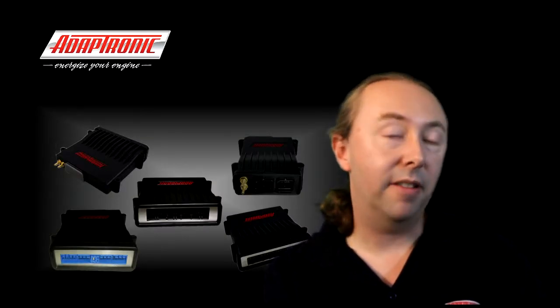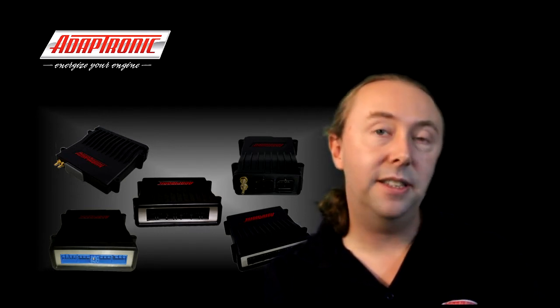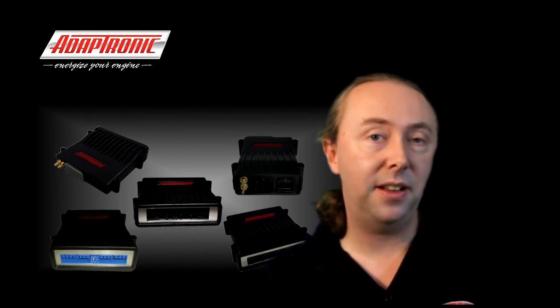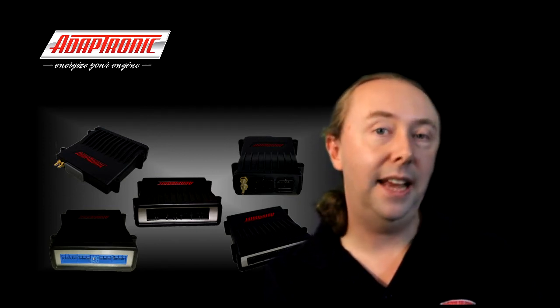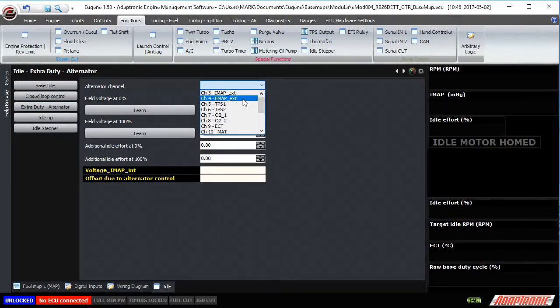So how much current the alternator is delivering, or how much load it's putting on the engine, therefore. So for example, if the alternator regulator is built into the ECU rather than the alternator, for example on the NB and later MX-5s, on the Dodge SRT4, on the Mazda RX-8 and so on, and the 86 FRS BRZ, then for the plug and play ECUs, the alternator control provides an input to the ECU, and you can use that to control the idle effort.